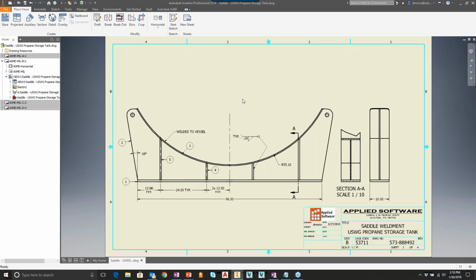All right, so the next thing we're going to look at, the next tip, is going to be selection priority. And specifically when we're looking at a drawing, we may want to make changes to multiple dimensions at one time. So you can see here that I've got multiple dimensions in my drawing. I may want to make some sort of edit to those. Traditional method for doing that would be to select each dimension and then use the control click on the keyboard and go through and select each dimension that I want to make a change to. That can be undesirable for a large drawing with lots of dimensions. So what we can do is use this tip here.